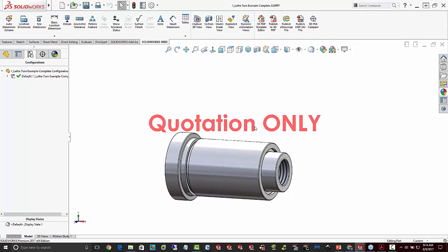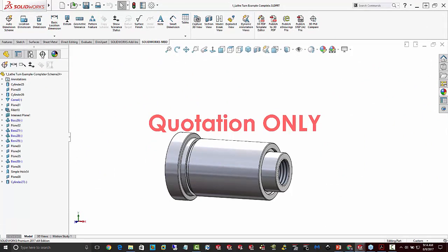Here we have a part that I've already defined using DimExpert. Inside the DimExpert tree, we can see all the features that have been defined. I personally like to show this as the annotation view, and then I can see the dimensions that have been defined. I can see the datums, etc. And I can usually see the GD&T callouts, such as the concentric here.